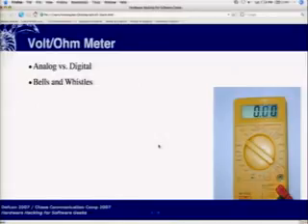Otherwise, these are fantastic. The basic ones, you'll just get ohms and volts, you measure resistance and voltage, current, usually a diode or continuity check. You can get all sorts of crazy features. Capacitance meters are pretty common. Some of them have temperature sensors via thermocouples, which are useful for controlling your toaster oven. No contact voltage. Oh yes, clamp meters for going around something that you believe to be carrying a current, which can pick up the current by induction.